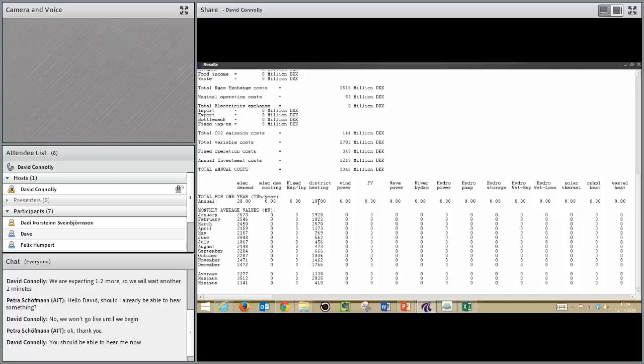And you can see that I have a total demand over the year of 10 terawatt hours, which is what I expected. And then at the bottom, you can see that it gives you the average heat demand over the year, the maximum heat demand over the year, and the minimum heat demand over the year. Here we can see that the maximum heat demand on the district heating system was approximately 2,000 megawatts of heat. So in the golden rule that I mentioned earlier, I said that we usually estimate the boiler capacity as 120% of this maximum heat demand of the year.